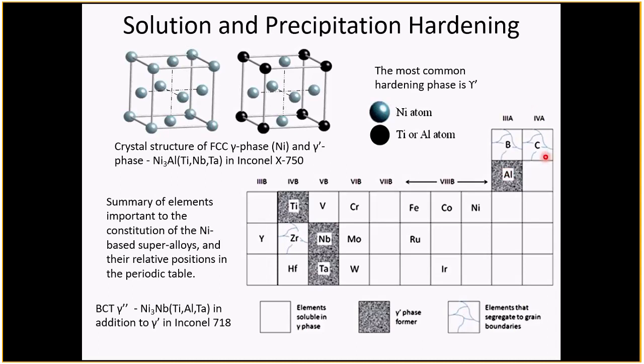And the solution to that is just keep heating, in fact, because then the remainder of the chromium in the bulk of the phase will diffuse into these depleted chromium phases once all the carbon's been used up.